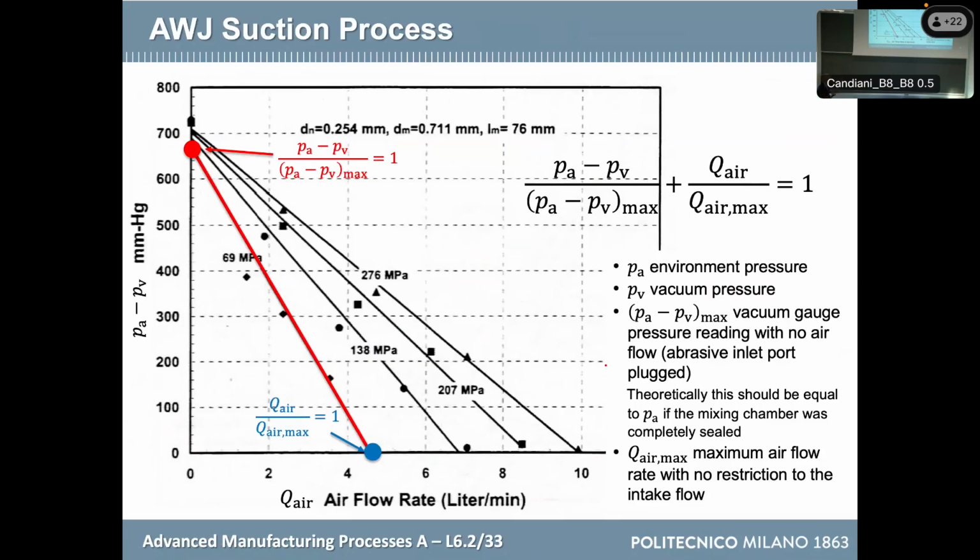But I decouple them because the hopper on board of the mixing chamber first defines the flow rate by gravity. For example, there is a hole, and the amount of abrasive depends just on the gravity, and only downstream I'm sucking that abrasive. So if I'm sucking more air, simply more air is entering, but it is not dragging more abrasive, because the abrasive has been decided by just the hole and the gravity. So this way I decouple them.